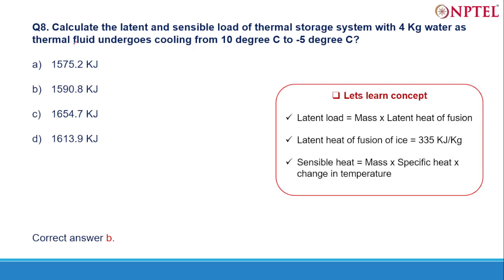And the last question, calculate the latent heat and sensible heat. This question I put just to make you understand the thermal storage system. So you know latent load is that heat that is taken in or out from the system without any change in temperature. If we don't have any change in temperature, that heat that goes into the system or is taken out is latent heat. But if there is a rise in temperature, even if it's 0.1 degree Celsius rise, then we will say that there is a sensible load. Okay, sensible heating or cooling has taken place.